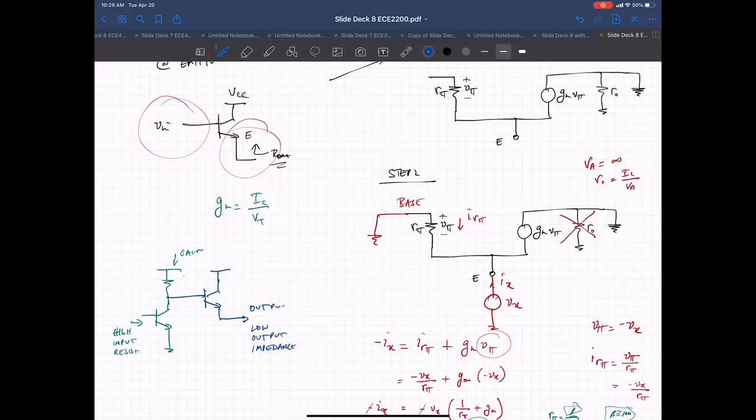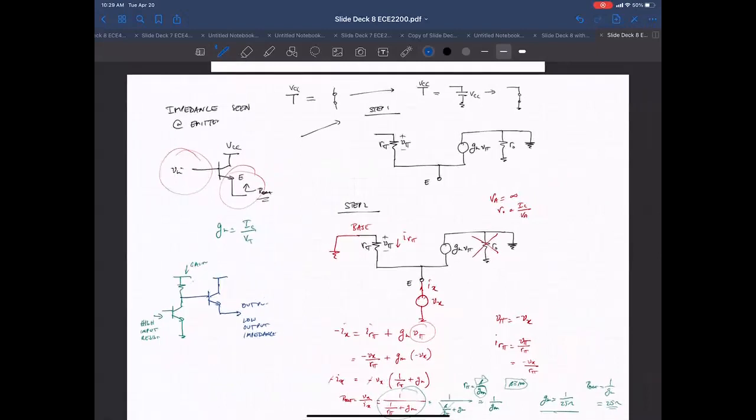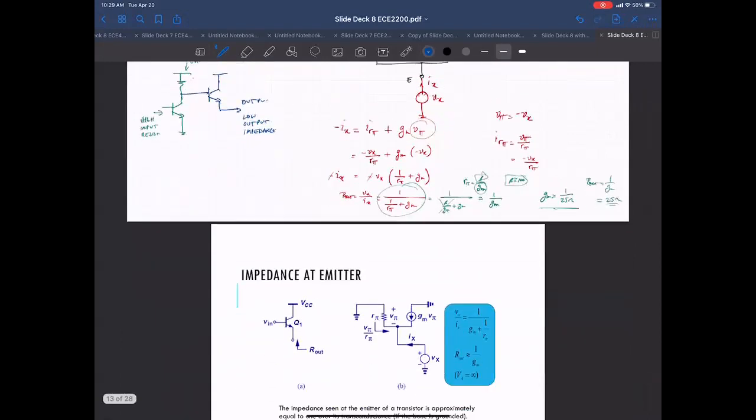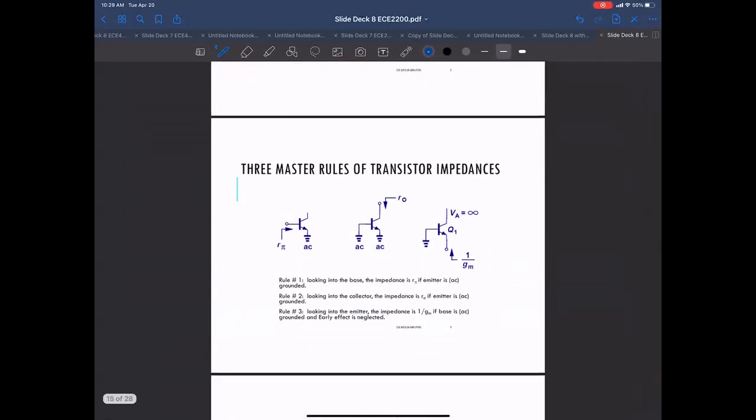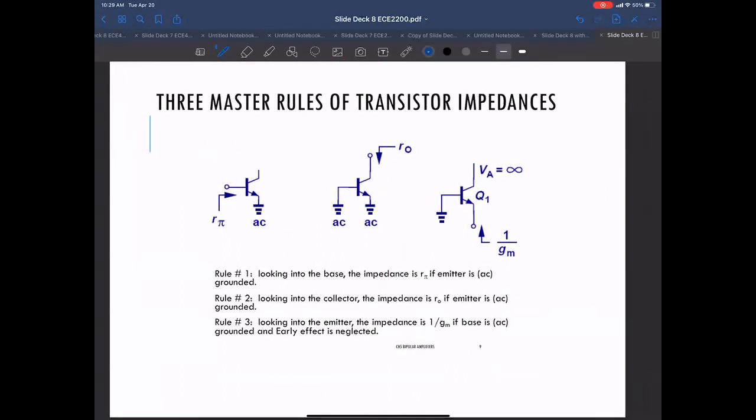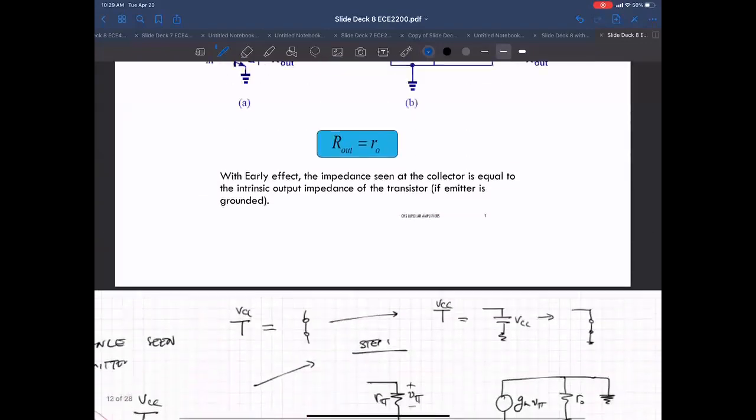various other things, linearity, there's a lot of stuff to consider, but they're made up of these stages, single transistor stages or things like that. And they give you different characteristics. So that was the emitter impedance of an emitter output. And so that's where we're sort of stopping with impedances, okay? And the procedure is very simple.